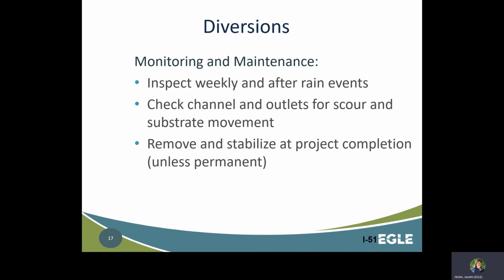Diversions must be inspected at least weekly and after each storm event. Any areas of erosion need to be repaired right away. Most diversions are temporary and need to be removed at the time of project completion. The area where the diversion was located would then need to be final stabilized.